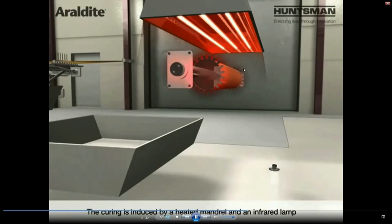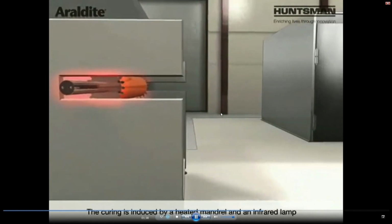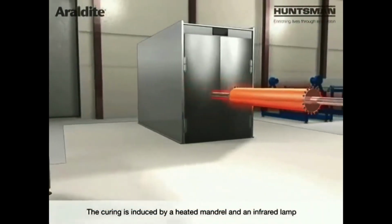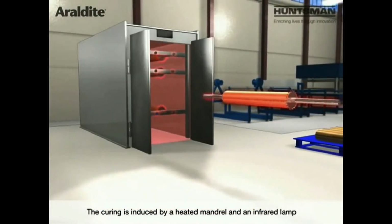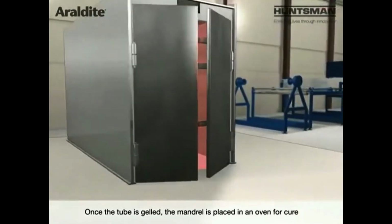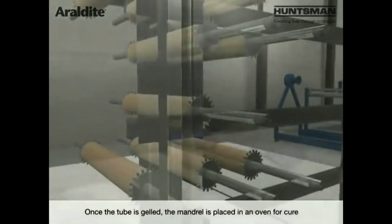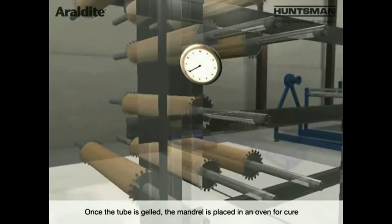Once the requisite thickness has been achieved, we will cut the fiber input and then we will heat it with the infrared lamp. Along with the mandrel, we will put it in an oven and after a requisite amount of time, this is the curing process going on.